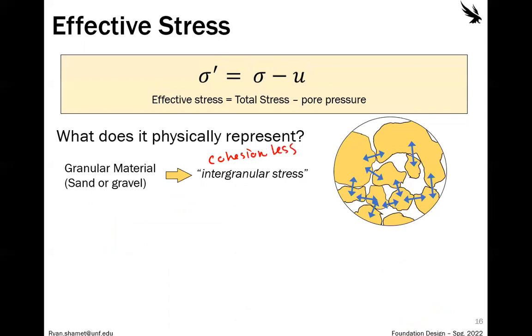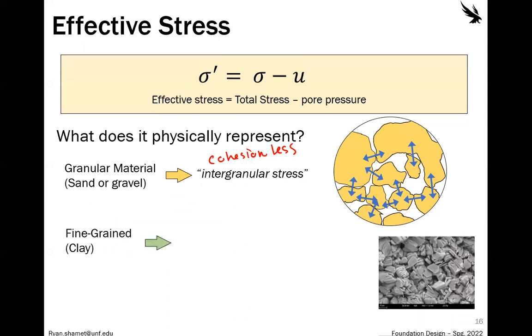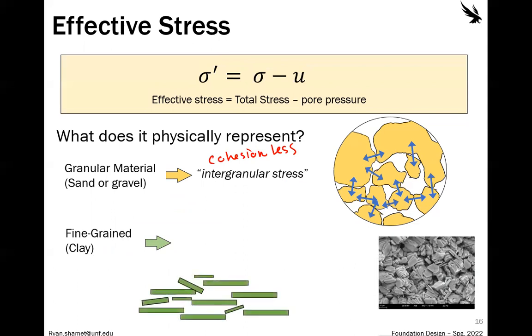You remember we were saying another type of soil is fine-grained soil, the clay. This is generally the cohesive soil, so what this physically represents is a little bit trickier. Clay material is super, super small. It's basically a bunch of plates sticking on top of each other, so it can't be visualized as small little rocks. This is an issue because they are physically not touching. The mineral crystals have no physical contact, since they're supported by electrostatic forces separating them, almost like little tiny magnets.